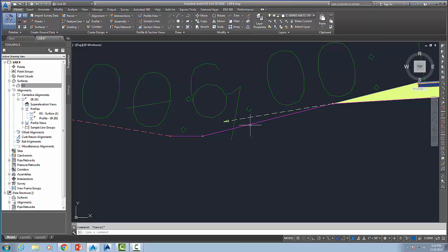So in other words, this slope is not constant here. What may be happening is this is kind of acting like a hinge point, and you have a profile that the ditch is following. So we can attach another attachment point to this, to a separate or secondary profile that the ditch can follow, and also a horizontal alignment that's associated with that.